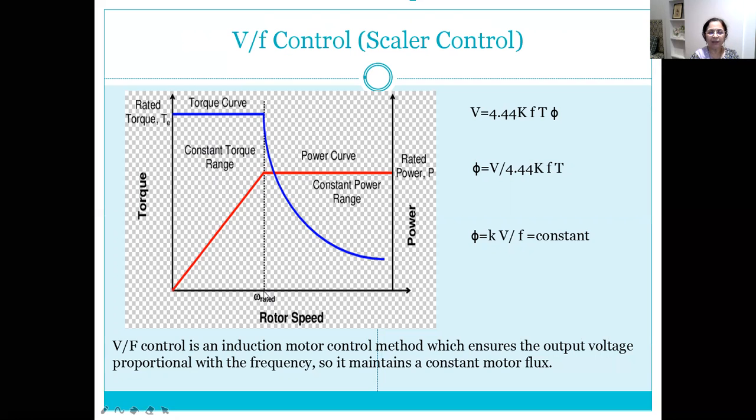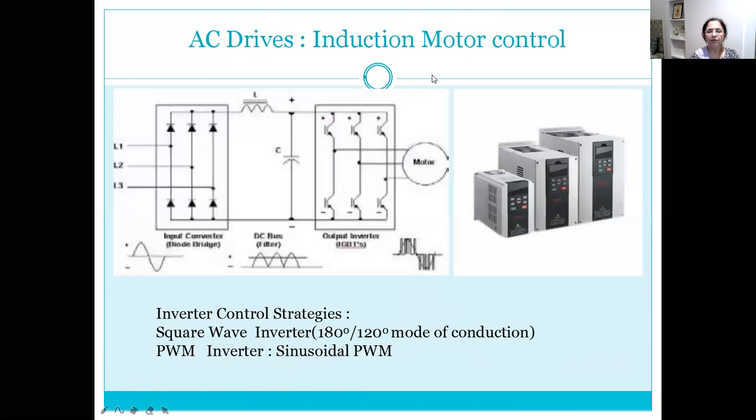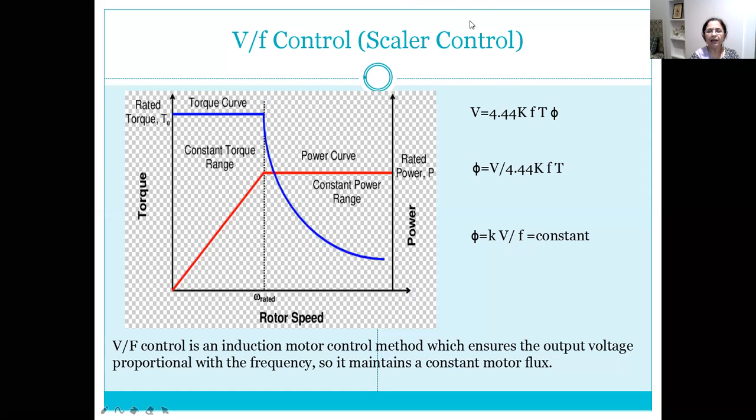Whereas when we try to operate it above rated speed condition, we cannot increase the torque, but the torque needs to be sacrificed or reduced proportionately, where power will be maintained constant. And so if we start looking at the expression, which is a well-known expression, we understand that this relation can be used by writing equation P equal to torque into speed, P = ω × T.